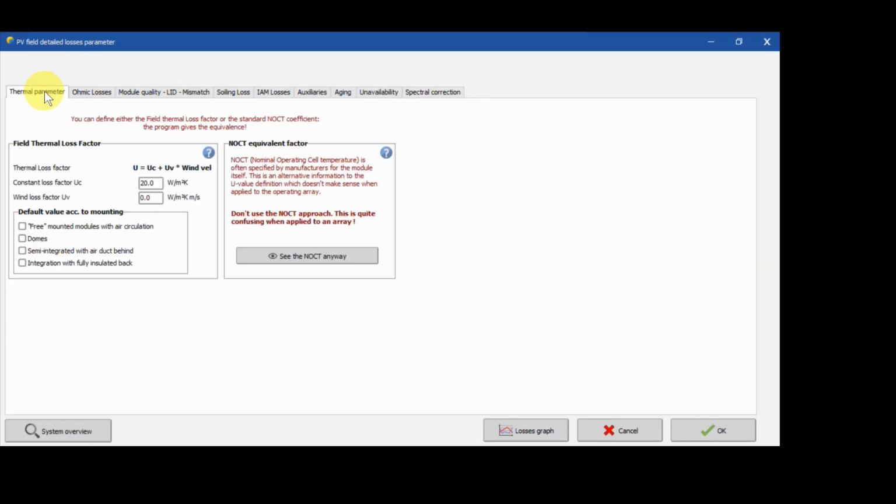Okay, this is the loss due to the thermal parameter. Basically, in PVsyst, for the losses, even without us doing anything, it has already made some loss assumptions in our initial report generation just now. So there are already default settings available for the losses. Under normal simulation, you don't need to modify any of the parameters here. Your result will still be valid with some tolerance level.